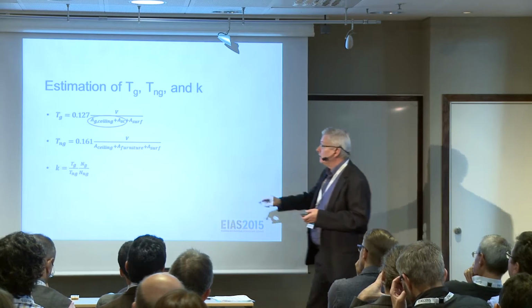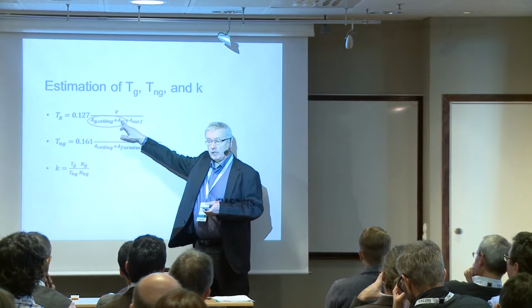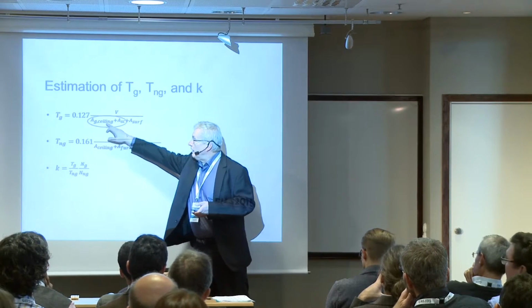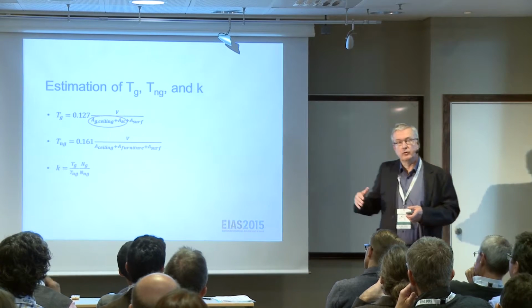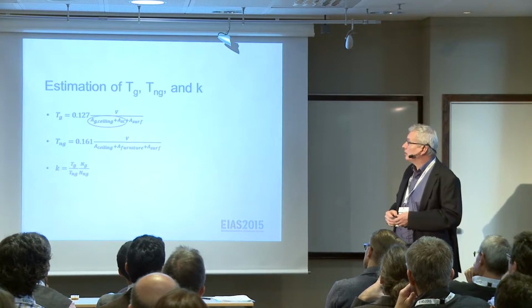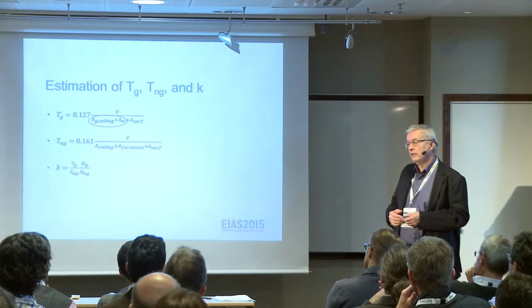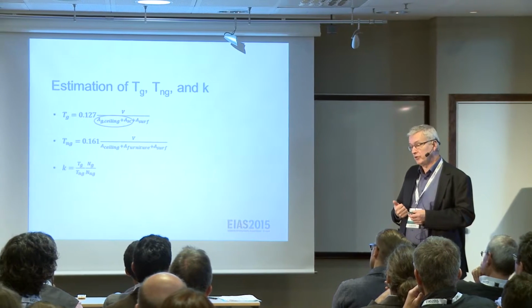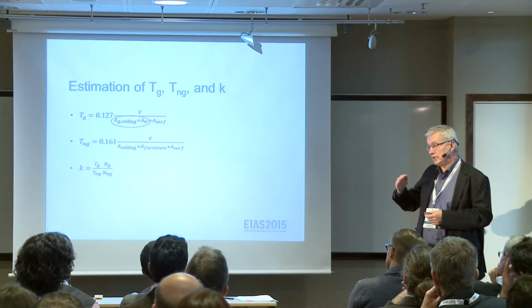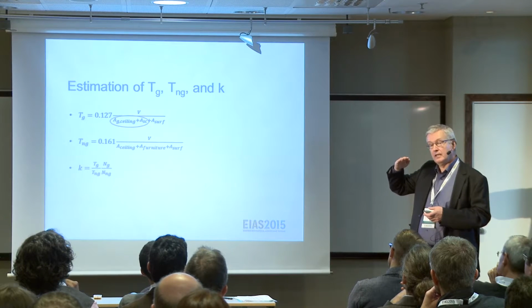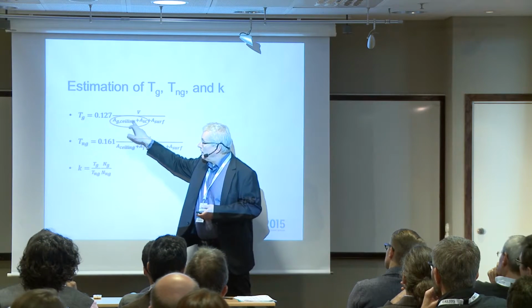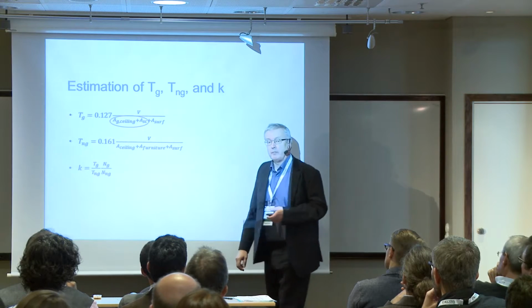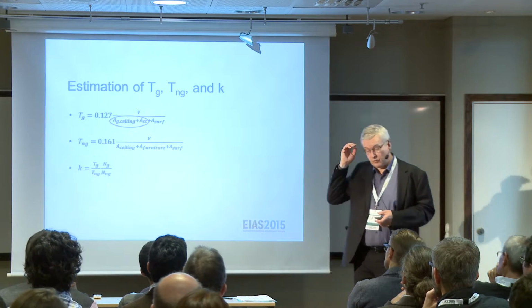Then I will show you later, we can estimate the scattering. Another thing here is that, as you know, for a sound field that is more or less horizontal in the room, we can't use the normal absorption coefficient for the ceiling, because the grazing part is angle dependent, for very grazing incidence, that goes into this equation. So there also has to be some way to estimate the angle dependence for grazing incidence.